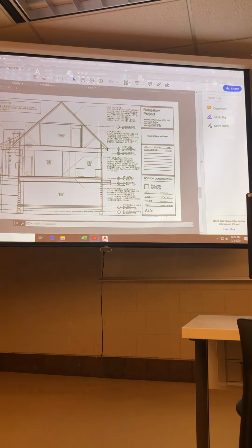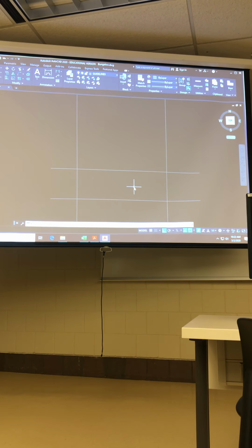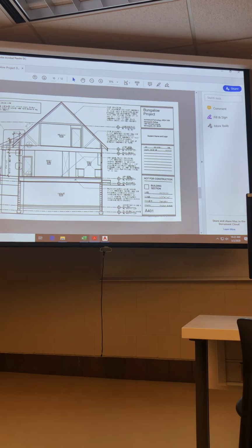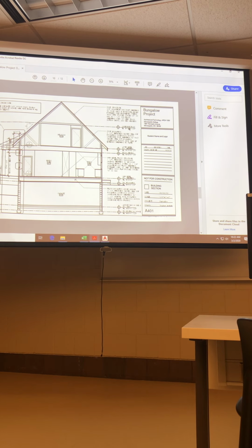So going back to my drawing, offset 10 feet, 8 1/4 inches from my main floor level, and voila, there is my top of sheathing for the upper floor level. I'm just gonna keep going vertically now to the next datum elevation, and that one is here at the underside of my roof truss, what would be the ceiling of the upper floor level.